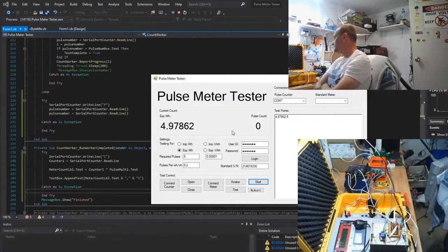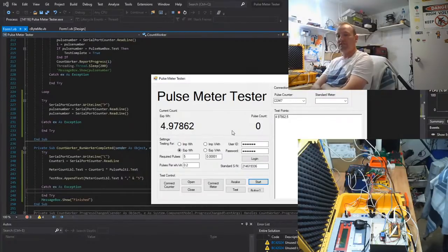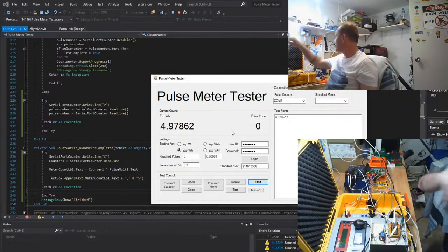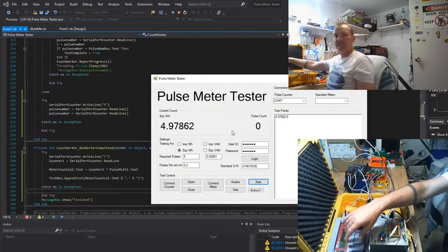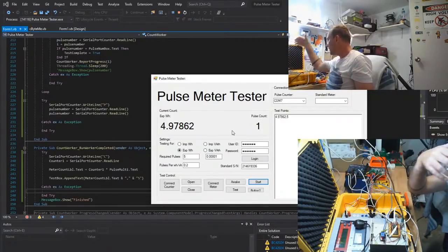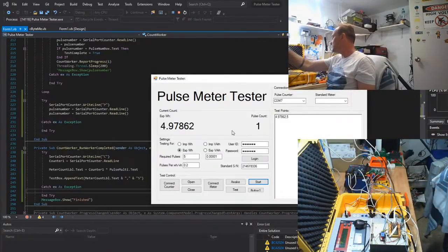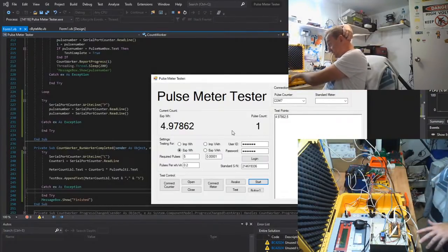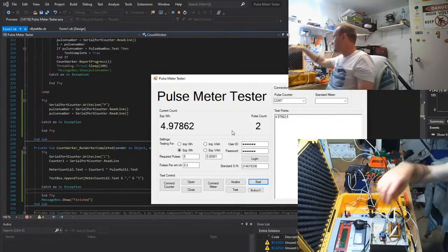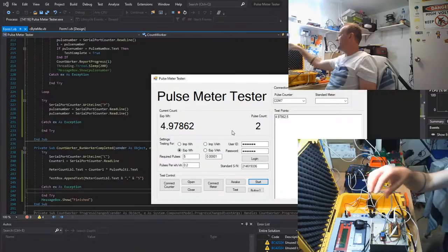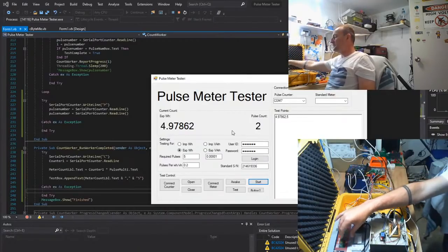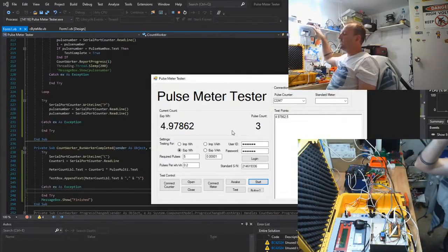It's still going, yep. I did actually make a program that calibrates many of these units against each other, so I can go to substations where I've got many of these and test each one against each other and add an extra one in. So that's what this yellow box is for. I'll put this in the circuit with many of them, and I can calibrate them against this one, and then I only have to calibrate this one against the primary standard.